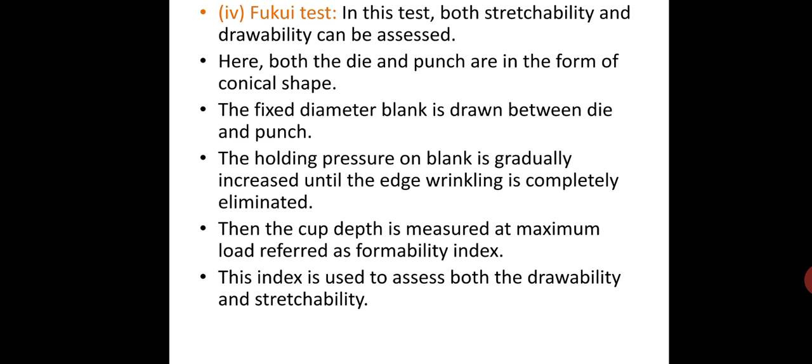The holding pressure on the blank is gradually increased until the edge wrinkling is completely eliminated. Then the cup depth is measured at a maximum load, referred to as the formability index. This index is used to assess both the drawability and stretchability.